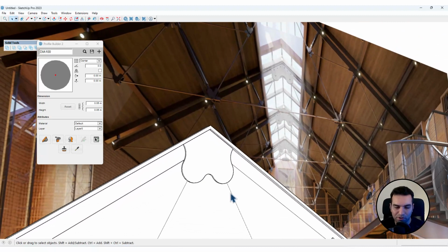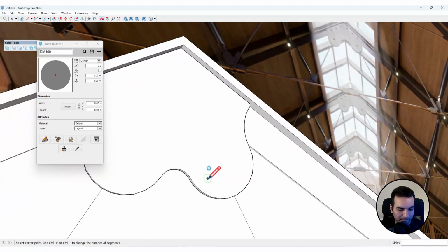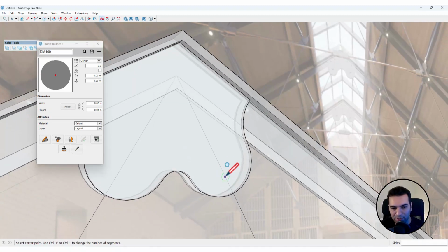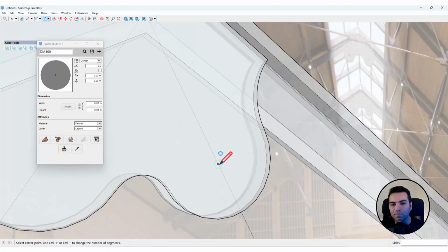And now we want to create the bolt, so I would hit Shift plus C to bring in the polygon tool, and then hit Y to activate X-ray. And then I would move my cursor on this edge and then find the center point and click and drag to create a bolt like this.